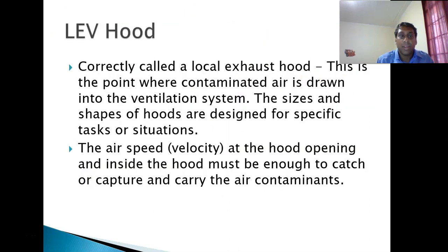So the LEV hood, correctly called the local exhaust ventilation hood. This is the point where contaminated air is drawn into the ventilation system. The sizes are for a specific task or situation. So if you want to explain some of this, the airspeed velocity of the hood opening and inside the hood must be enough to catch or capture and carry the contaminated air in.